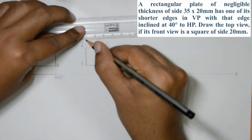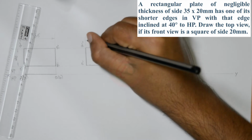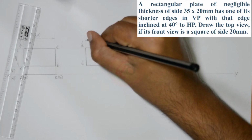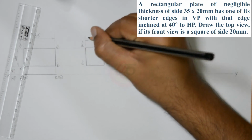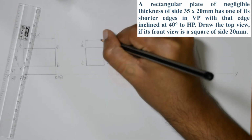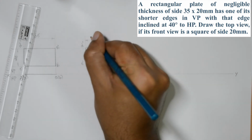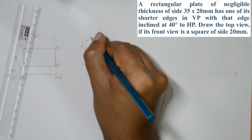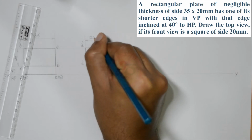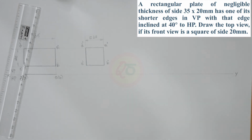So instead of marking dimensions for all the four edges, for the one edge itself, denote 20 with a square prefix. That would mean that the entire geometrical figure is a square of 20 millimeter sides. Okay.